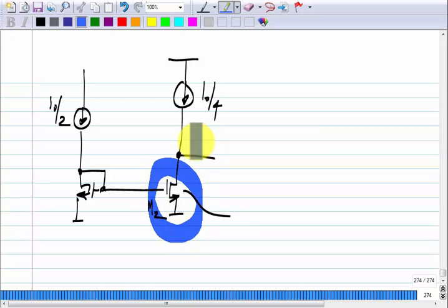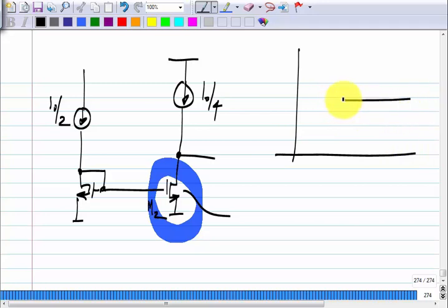So, a transistor, let us say its gate source is biased at some value, it has a certain saturation current for that gate source voltage. A transistor can have less current, obviously the transistor's ID VDS characteristics look like this, right. This is the saturation current, but it can have less if it operates here. So, it has to go into triode region. So, in this case the current will actually be I naught by 4 and it will be in triode region. Okay.